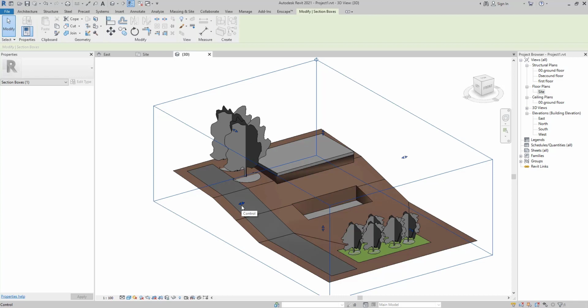section as you wish in your 3D view, because when we are, for example, in plan, we can use the section line, which you can find here. Or if we are, for example, in our elevation, we don't need a section. So section box works for 3D view. And we are going to move this arrow here to the inside of our work, and let's see what will happen,